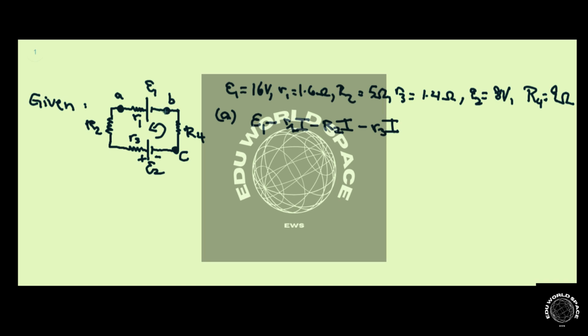Over here we're going in the opposite way, from the lower potential to the higher potential in terms of the battery, so we're crossing the battery in the opposite way. So we have to put a minus sign to account for that. And then we have a voltage drop here, minus R4I, and that's equal to zero. So that's the sum of all the potential differences in the circuit.